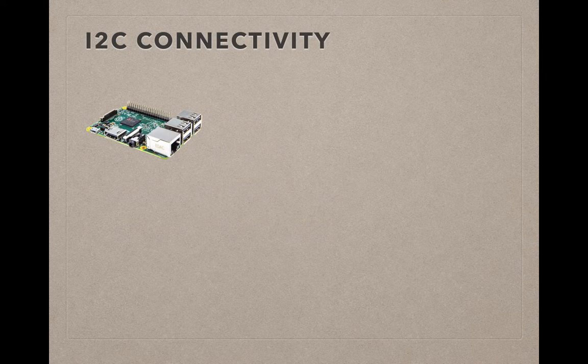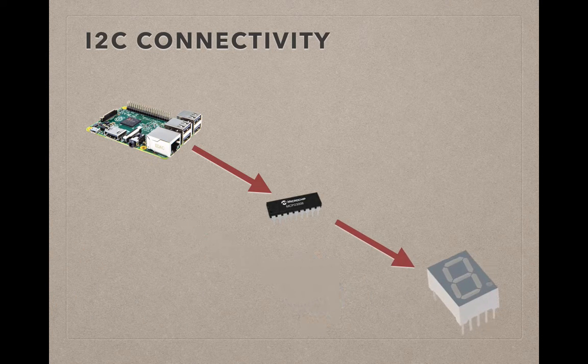What I am going to create in this series of videos is an I2C connection from the Raspberry Pi to a 7-segment LED display using an MCP23008 integrated chip to perform the actual controls. The 7-segment display actually has 8 controls if you include the decimal point, so the MCP23008 is the perfect choice to control it, as it has a total of 8 configurable pins. I could also use the MCP23017 chip, which has the same configuration but offers 16 configurable pins.